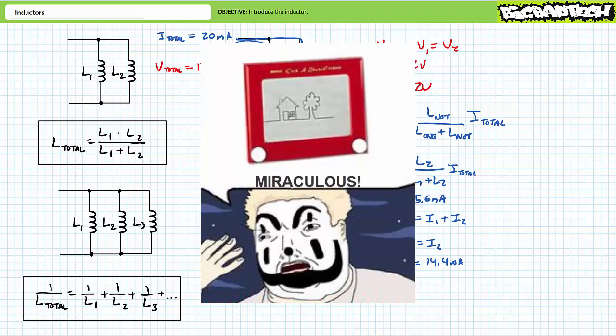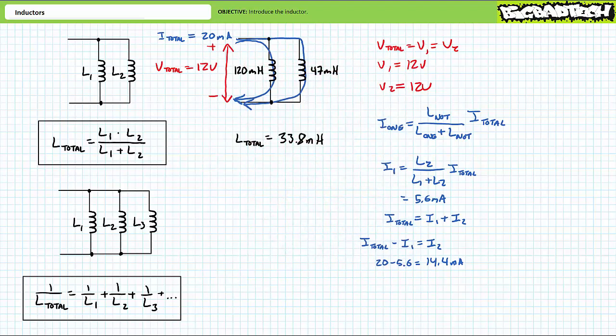and electromagnetic interaction. In conclusion, we introduced the inductor, an electrical device that can store energy inside a magnetic field inside a coil of wire. We examined basic electromagnetic interaction, the concept of inductance, inspected inductor construction, discussed how properties like cross-sectional area, number of turns, coil length, and magnetic permeability of the core influence inductance. Additionally, we briefly discussed the shoddy and unpredictable means manufacturers use to label inductors and how to measure inductance using an LCR meter. Finally, we learned to calculate total impedance of series and parallel relationships of inductors.